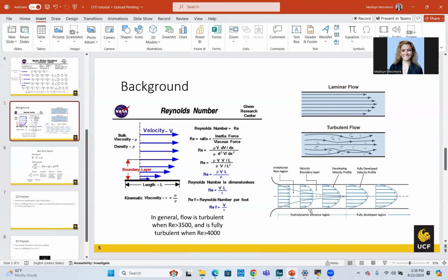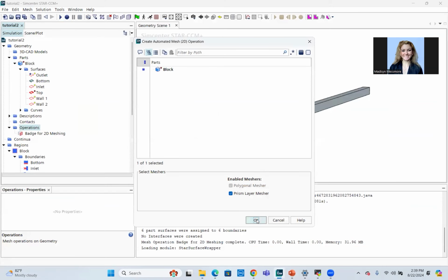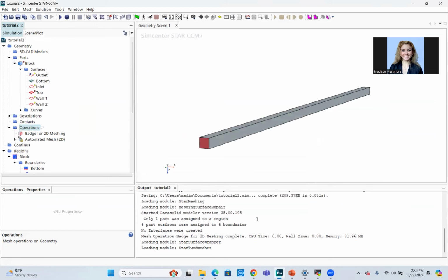And so if you only solve your equations in big chunks, say only at the halfway point and the midline, you're not going to get all of the detail that happens in that rapid change. You want to see everything. So you're effectively refining your resolution. If you think of measuring something with a tool, you want your resolution as fine as possible so that you can see all of the details. That's really all we're doing with this. So prism layer adds resolution at those high-change areas, and you can adjust the number of them, which is cool.